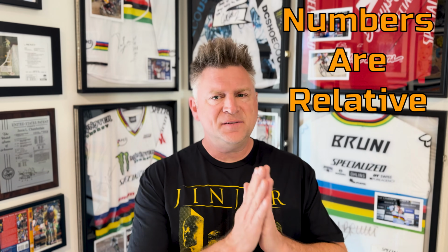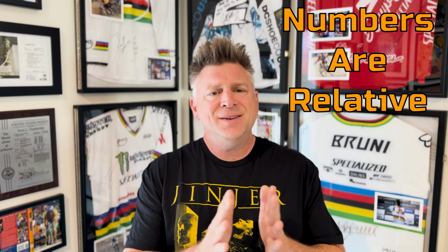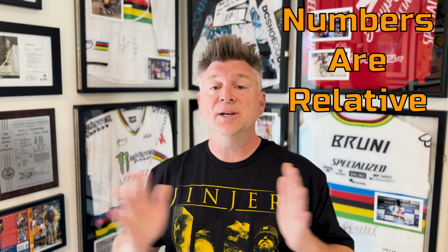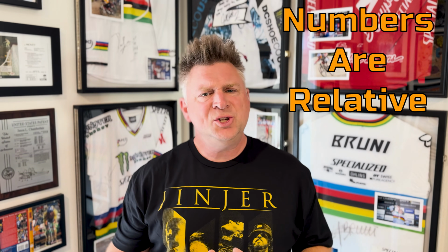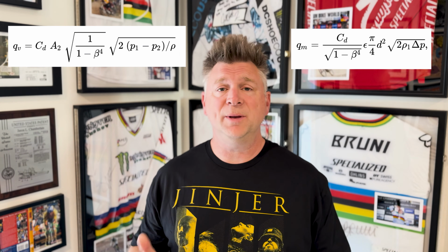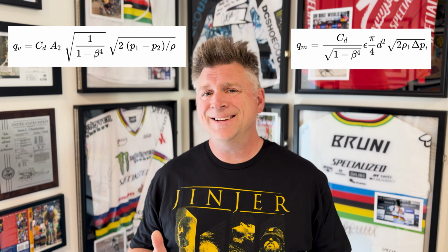Say your baseline is 50, well, 55 is a little slower. 60 is a little more slow. 100 is twice as slow. You're going to tune in a relative manner anyway. There are super complicated equations that predict oil behavior and oil flow, but it's way too burdensome. You're going to figure out your oil weight through testing.